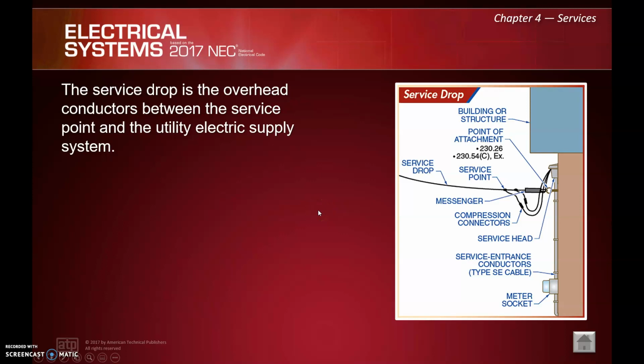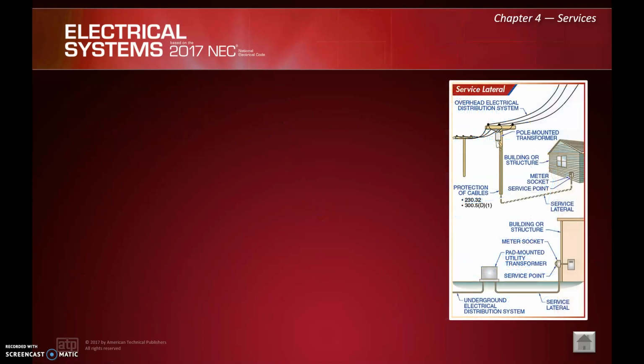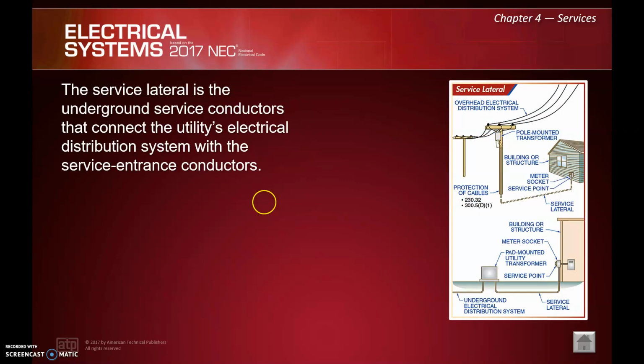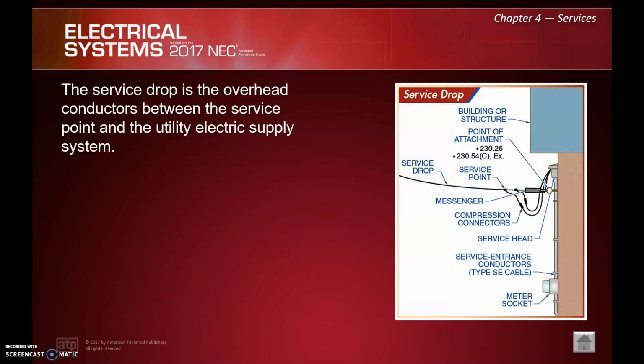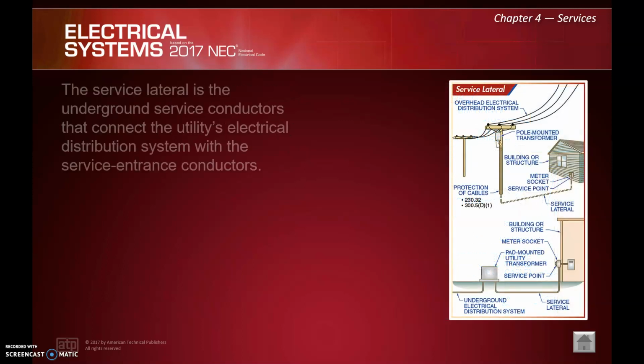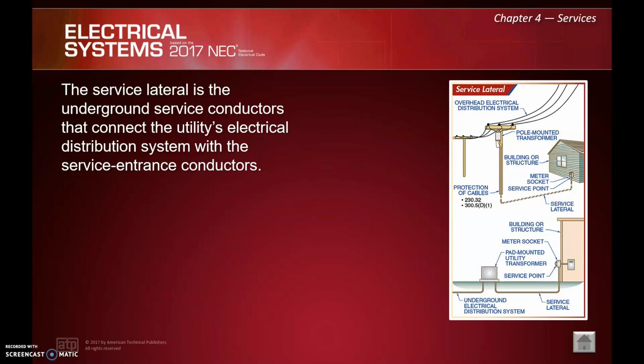electric supply system. Okay, and sort of the opposite side of that would be the service lateral, which is then the underground service conductors. So again, just to reverse here, we have service drop overhead. Service lateral is going to be underground, right?